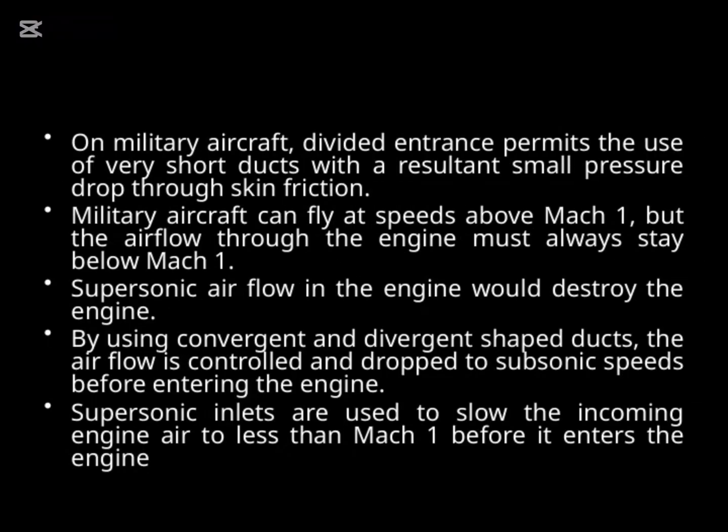On military aircraft, we often see a divided entrance design, which allows for the use of very short ducts. This design is crucial because it results in a smaller pressure drop due to skin friction, making the engine intake more efficient. Even though military aircraft are capable of flying at speeds above Mach 1, the airflow through the engine itself must always stay below Mach 1. Why is that? Because if the airflow inside the engine becomes supersonic, it would actually destroy the engine.